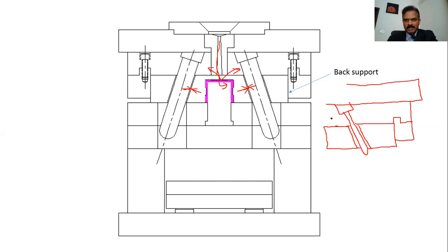Now the mold is moving up. So the finger is going to move up, right? So when the mold moves up, the finger will push this outside. It is going to definitely push this away. But can it move? No, it cannot move because this is a straight line. It is in the way, right? Until this line covers this point, definitely something is in its way.